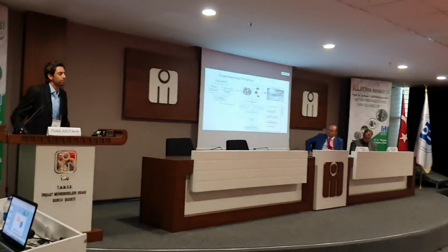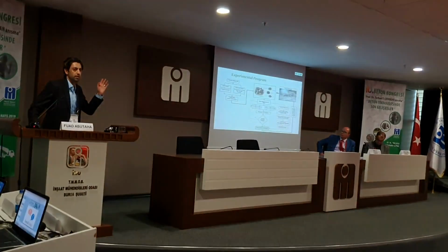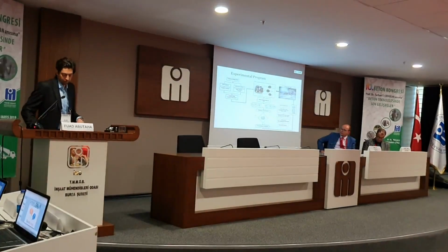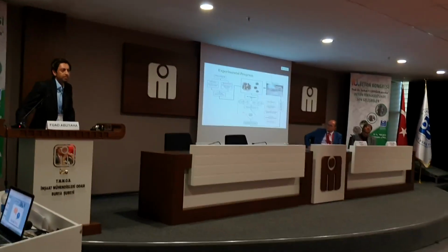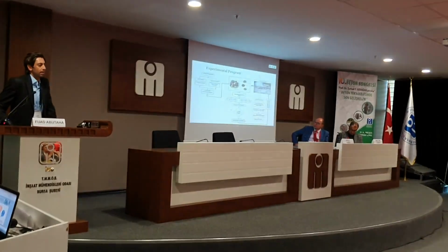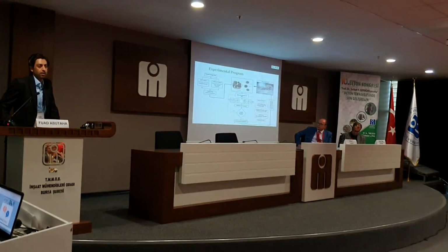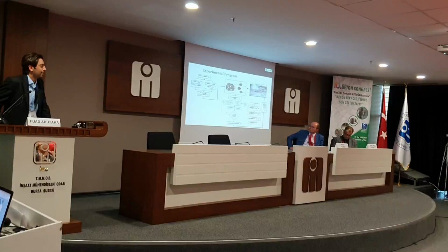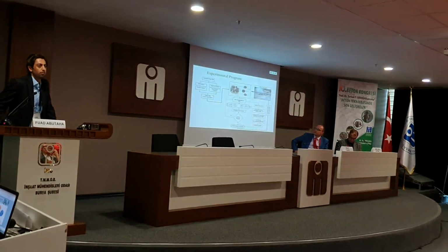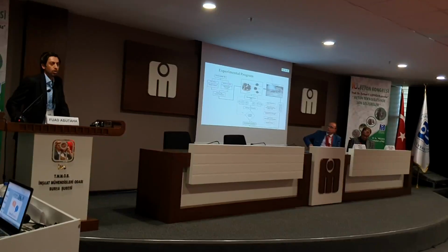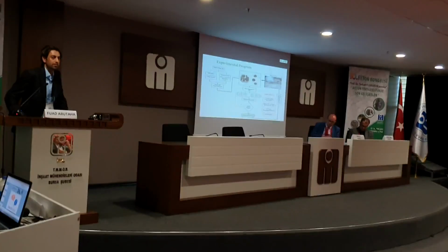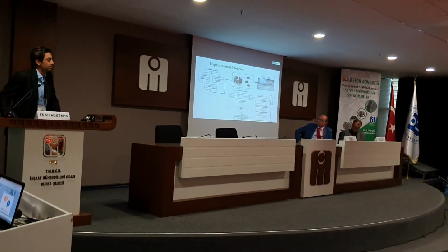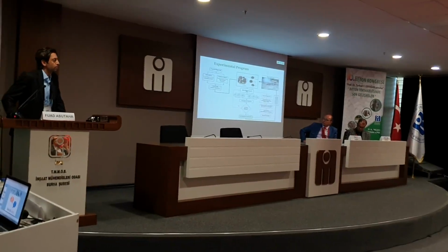The replacement was conducted by volume. The replacement level ranged from 0 up to 20, 40, and up to the full replacement of the coarse aggregate for both grades. Because of the properties of this material, which is very lightweight, porous, with a lot of voids and sharp broken edges, it negatively affected the fresh and hardened properties of the concrete. This was the first experiment that was conducted, and we observed this negative effect.